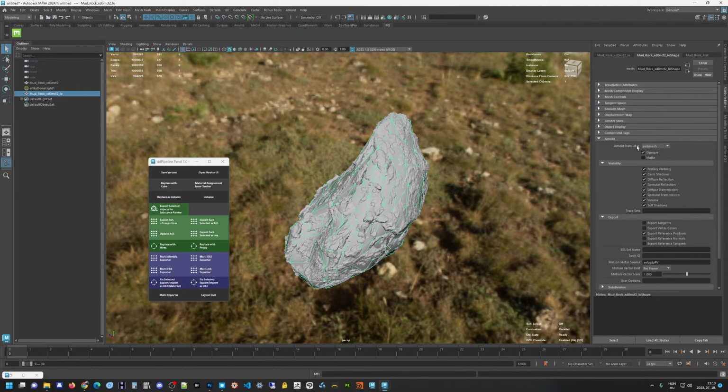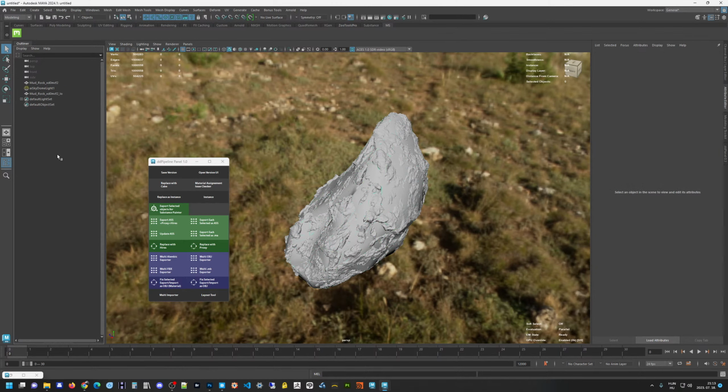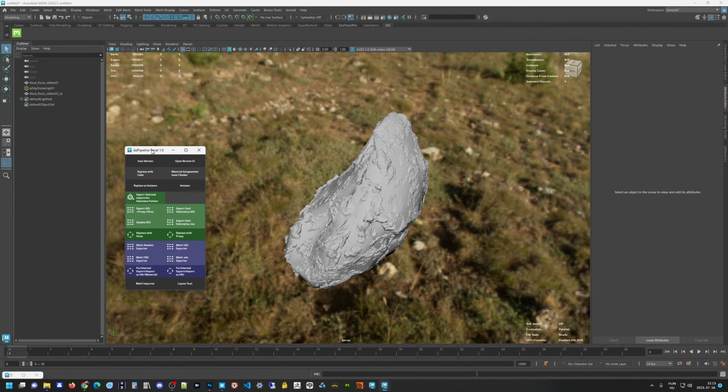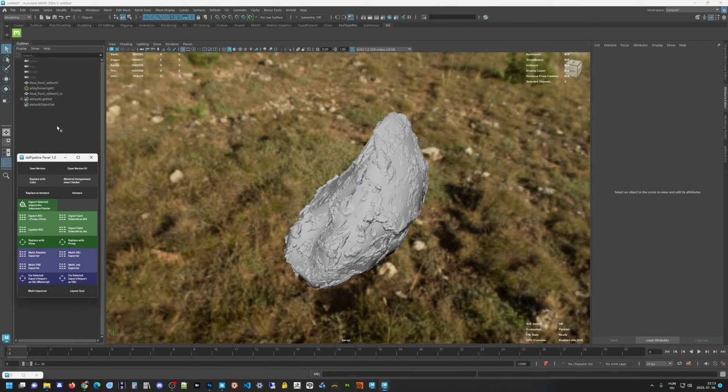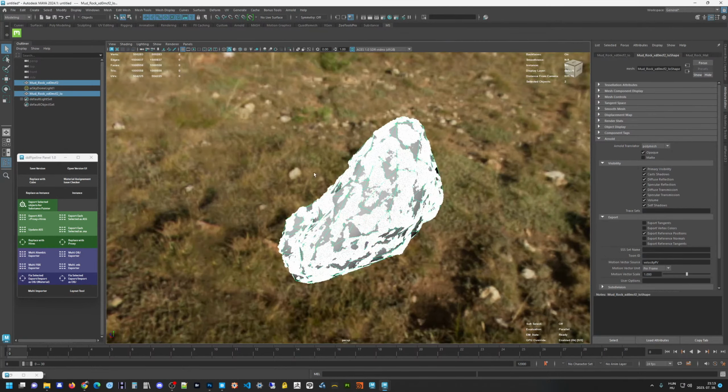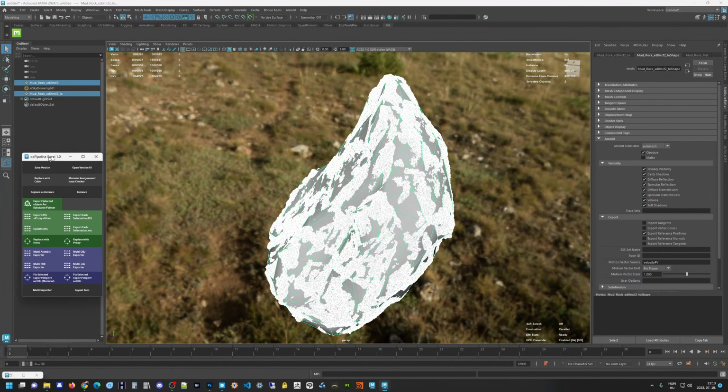It will switch the Arnold translator to the procedural part, and then link the previously exported ASS file to here, and then it will export the high resolution geometry with the original material, and it will export the low resolution geometry as a proxy file as well. So it will create 3 different exports, and you can use those anyhow you want, but the system is providing a few simple ways to do that.